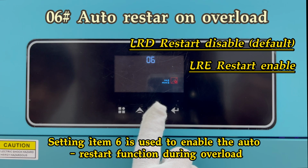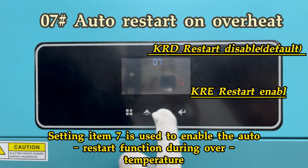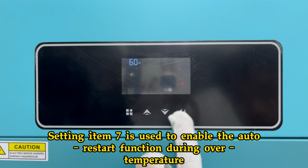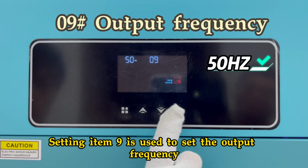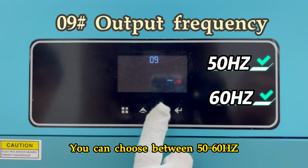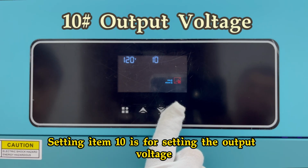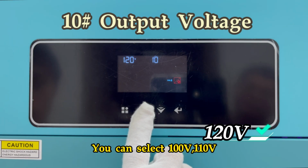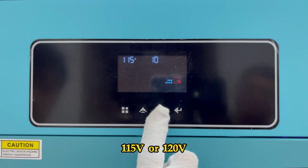Setting item 6 is used to enable the auto restart function during overload. Setting item 7 is used to enable the auto restart function during over temperature. Setting item 9 is used to set the output frequency. You can choose between 50 and 60 Hz. Setting item 10 is for setting the output voltage. You can select 100 volts, 110 volts, 115 volts or 120 volts.